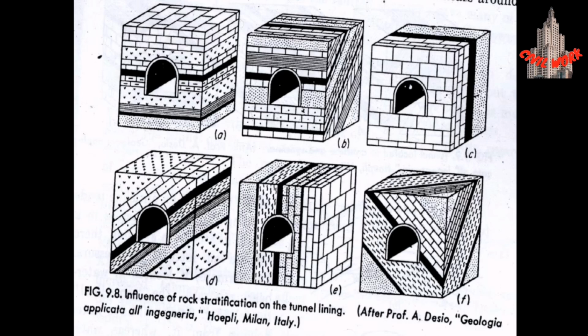First, we will discuss the horizontal strata, which is here. For small tunnels or for short lengths of long tunnels, horizontally layered rocks might be considered quite favorable. In massive rocks, that is when individual layers are very thick and the tunnel diameter is not very large, the situation is especially favorable because the layers would then overbridge the flat excavation by acting as natural beams. We can see there we have layers which are not very wide, but they act as a natural beam for the tunnel construction.